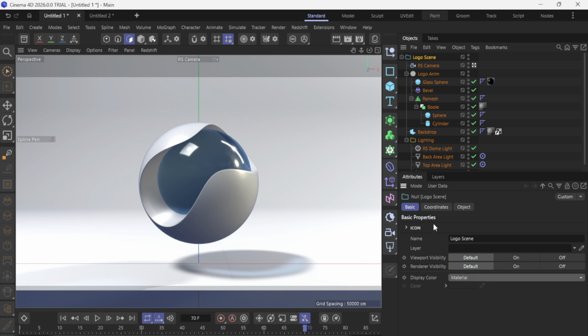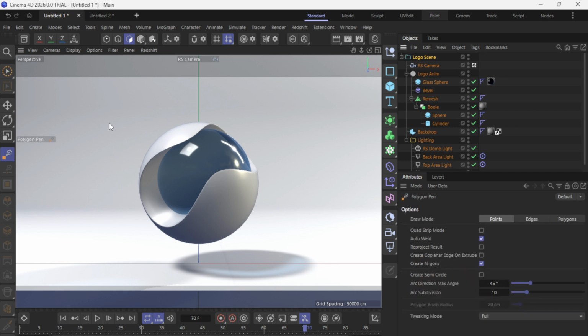You'll also see a choice to group the splines. Grouping collects everything under a single parent, which keeps the object manager tidy, especially helpful when your Illustrator file has lots of paths or layers. If you prefer to manipulate individual elements separately right away, you can turn grouping off. Either way, the geometry that comes in will be editable splines, ready for modeling operations.